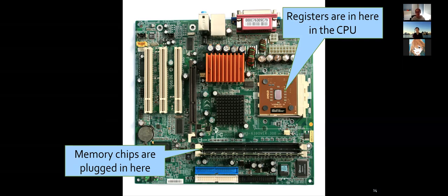When I talk about SRAM versus DRAM today, you're going to see that the SRAM design has no capacitor. Because it doesn't have a capacitor, it has to compensate by having many more transistors like inverters, and that makes the cell bigger and more power hungry. So the short answer is you can have a lot of SRAM as well, but the larger SRAM becomes, the slower it becomes.